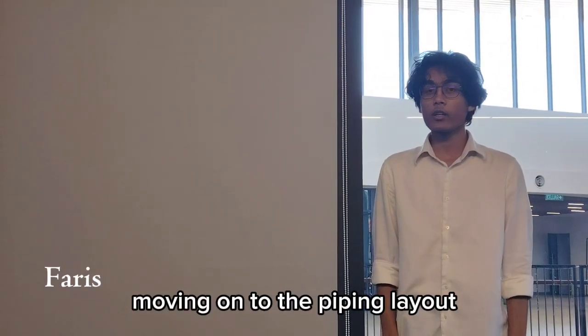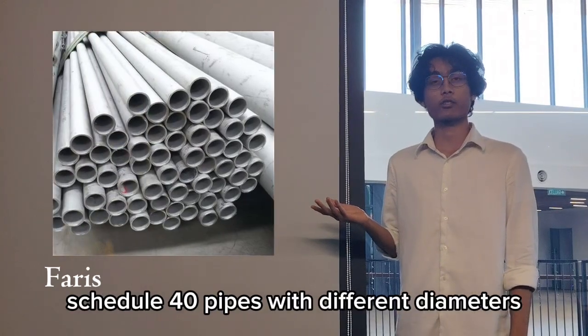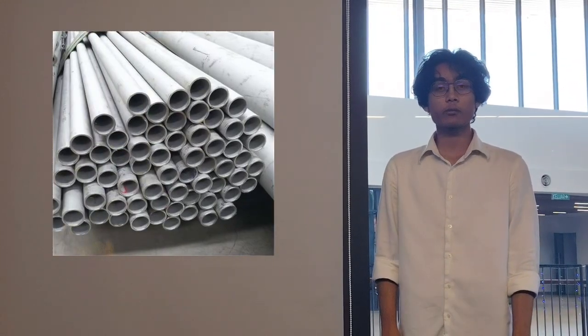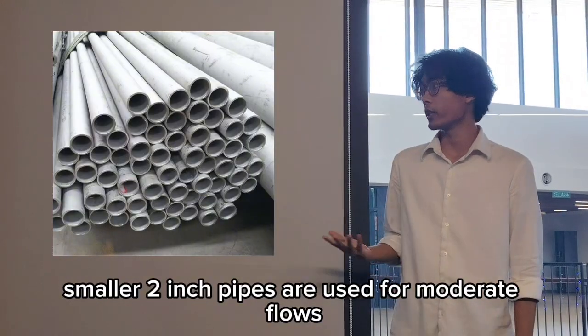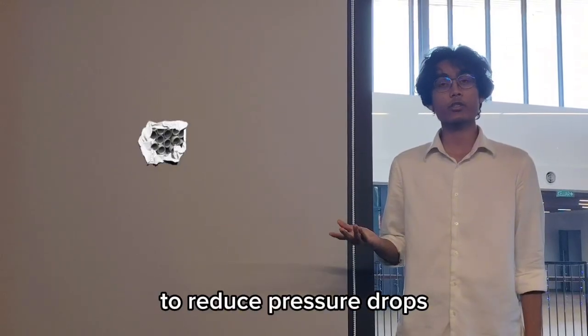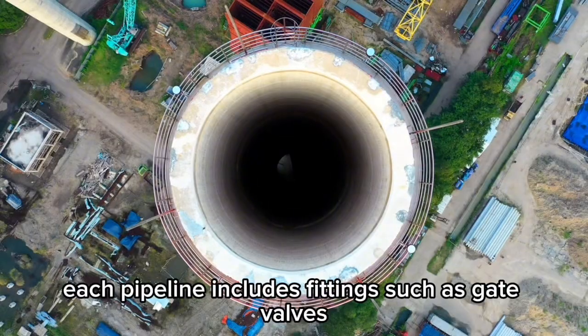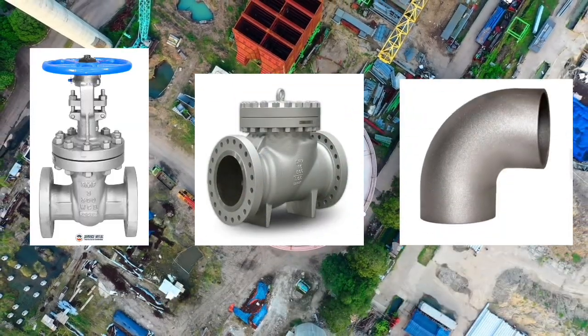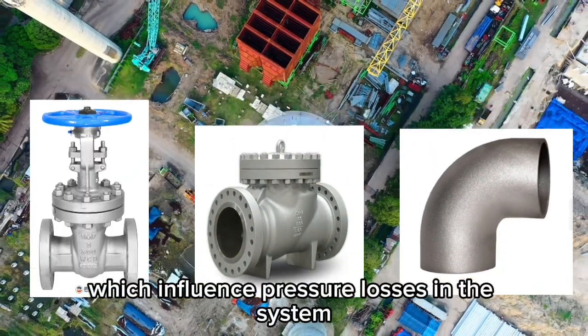Moving on to the piping layout, this process uses stainless steel schedule 40 pipelines with different diameters depending on the flow conditions. Smaller 2-inch pipes are used for moderate flow rates, while larger 3-inch pipes are used for higher flow rates to reduce pressure drops. Each pipeline includes fittings such as gate valves, check valves, and 90-degree elbows, which influence pressure losses in the system.